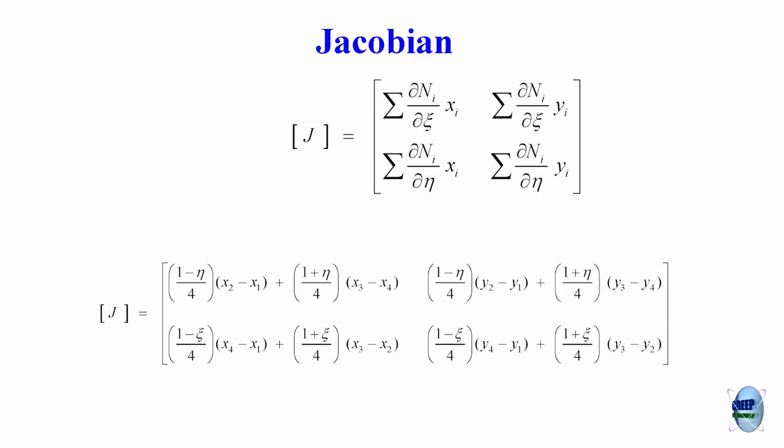It depended on the shape function derivatives and the nodal coordinates, shape of that element. When you have measured the whole geometry, it depends on these two things. So, given an element, that means the nodal coordinates being known, you will be able to compute this. But we notice that because this involves zeta eta terms, it would vary from point to point within an element, okay, note that.